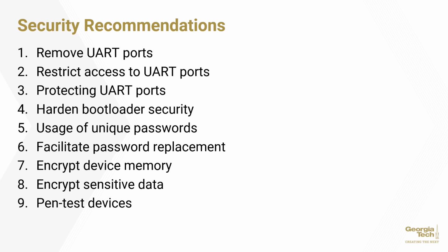to JTAG protection. Number 4 is that we can harden bootloader security using passwords or only allowing debug mode when a specific electrical criteria is met. And then we've also got to make sure that unique passwords are used per device and not just one password across the entire manufacturer.